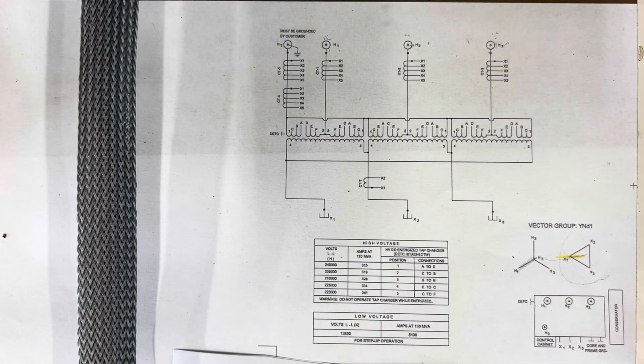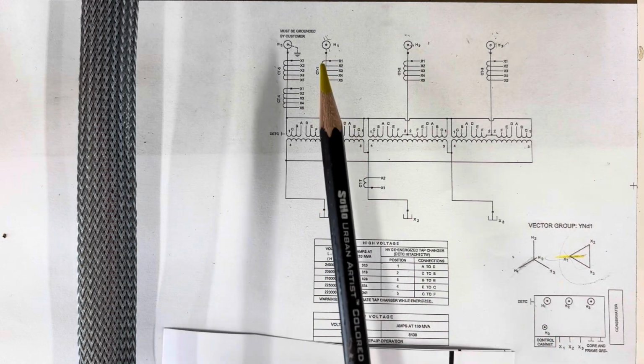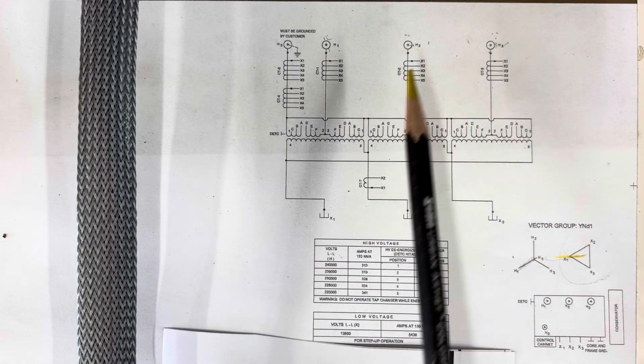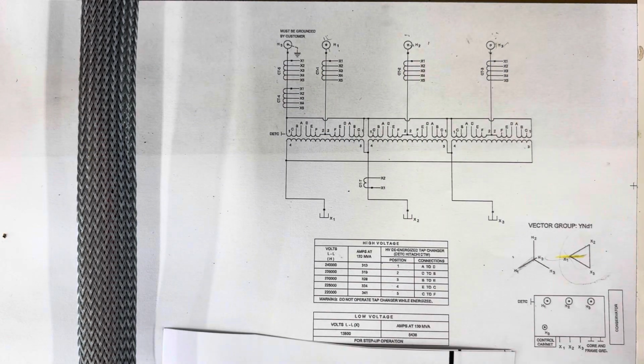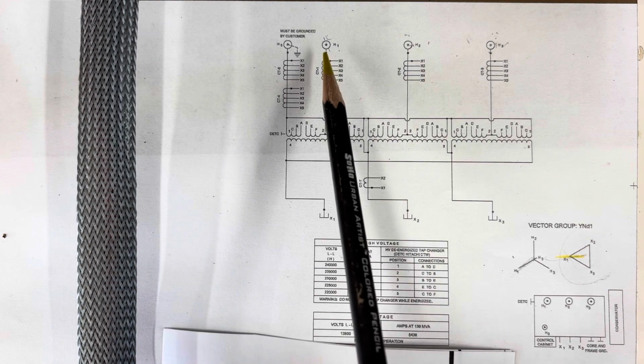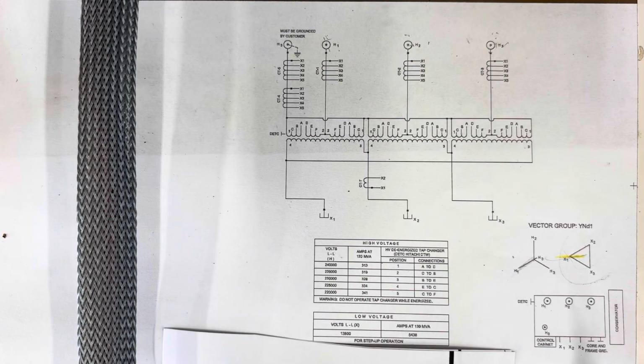Summary. On a transformer, if you want to maintain the vector group that is shown on the nameplate, you need to apply a phase sequence of 1, 2, 3, or 2, 3, 1, or 3, 1, 2, which are all basically the same thing. If you were to apply a phase sequence of 1, 3, 2, it would mirror the vector group, and you would observe, instead of, in this case, the secondary lagging the primary, it would lead the primary.